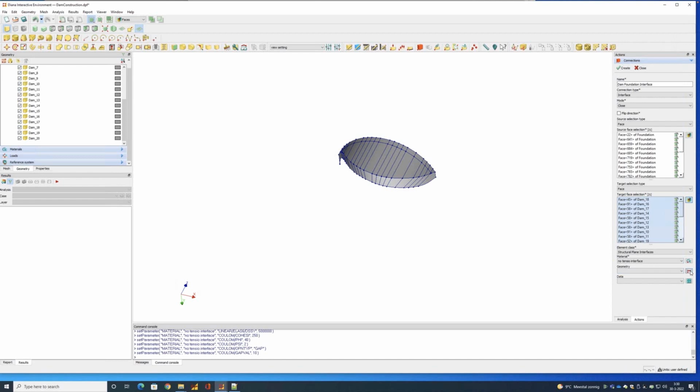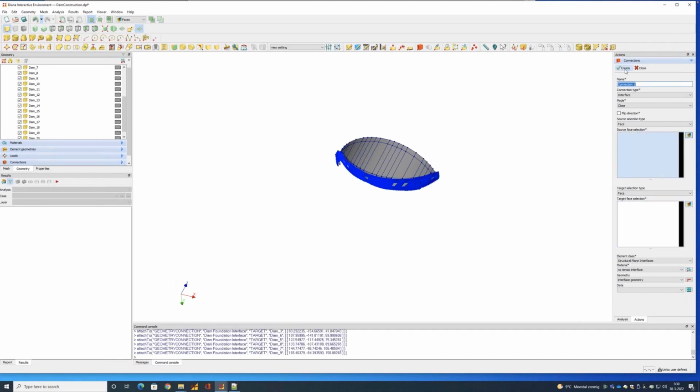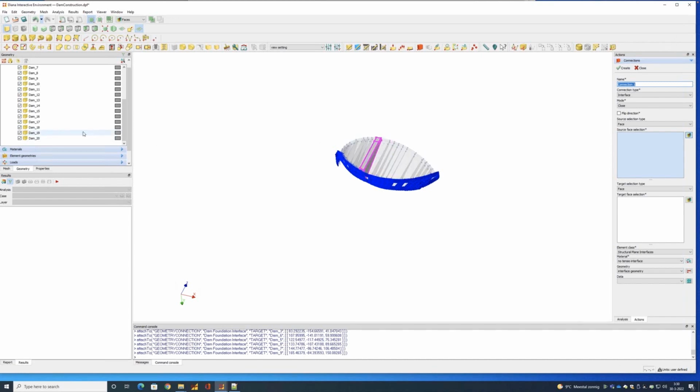So we need to create a geometry set. So interface geometry, and we will also use this face for this set for the other set of interface. And over there we define that the local element axis is in the y direction. And finally you click create. And you see that something is happening there. You see some symbol which represents basically one side of your interface.